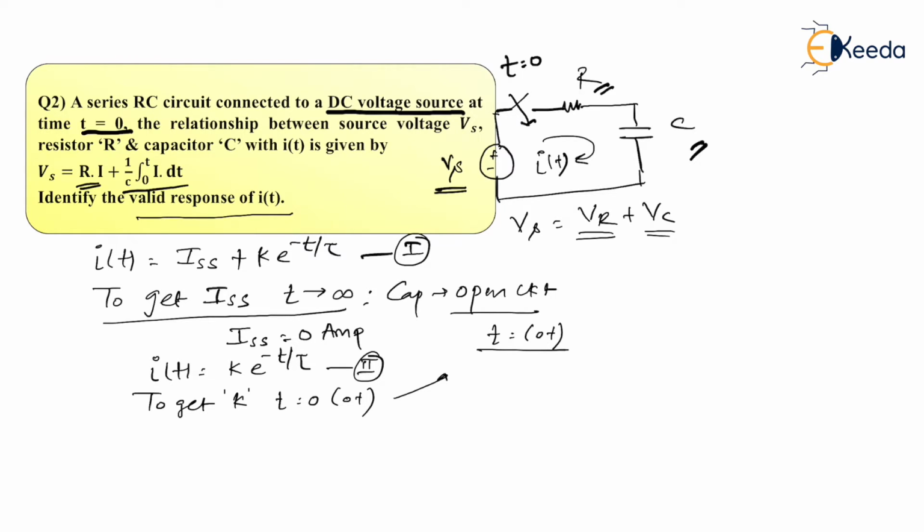As you could see, at t equal to 0, switch is closing. Meaning that for t less than 0, switch was open. If the switch was open, ask yourself, do you think your capacitor was getting charged? Answer is no, it wasn't getting charged. If it wasn't getting charged, can I say that V0 was 0 volt? It means initial voltage on the capacitor was straight away 0 volt.